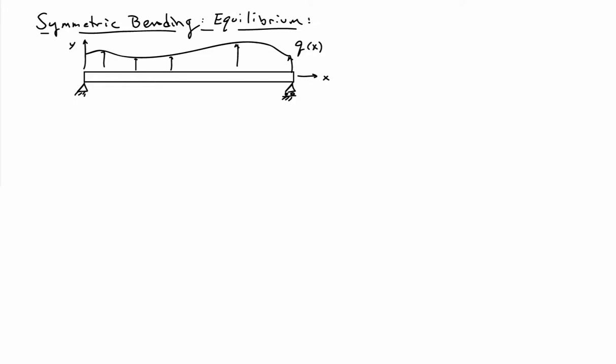Now that we have an expression for the basic kinematics of bending of beams, let's go ahead and look at the issue of equilibrium in beams. Equilibrium in beams is a fair bit more complex than the cases that we've looked at, and that's because of the greater variety of types of loads that we can have in a beam. Namely, we can apply both bending moments transverse to the axis as well as shear forces transverse to the axis.